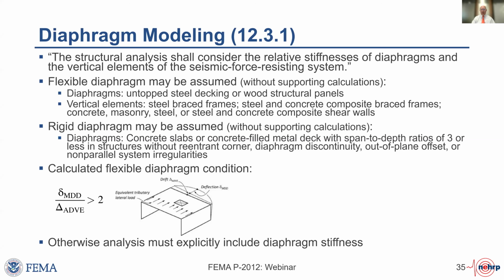But we mentioned before that although structural analysis and seismic response may be a complex problem, there are ways that we can simplify it at times. So there are some rules that you can apply without supporting calculations to decide that the diaphragm is flexible, infinitely flexible, and so load should be distributed on a tributary area basis. There are some other rules that say you can consider this diaphragm to be rigid without any calculations, infinitely rigid for the sake of your design.